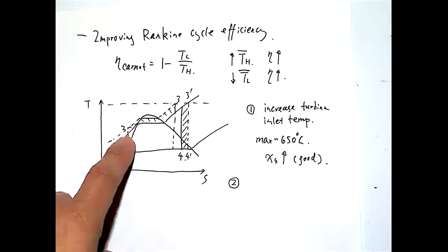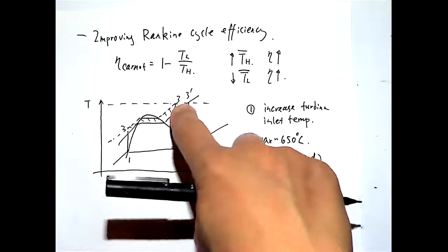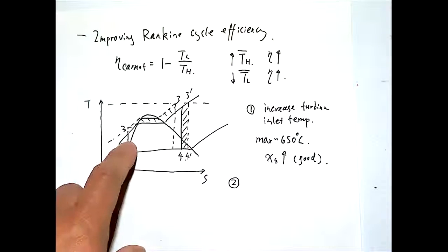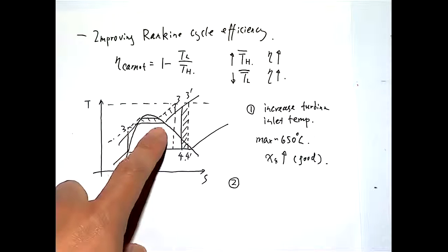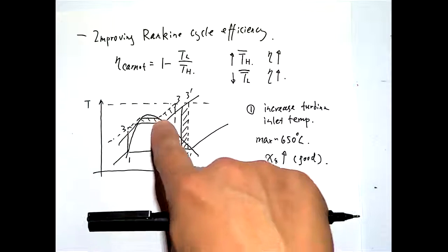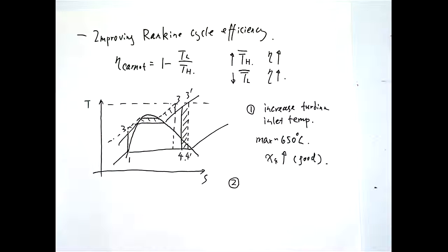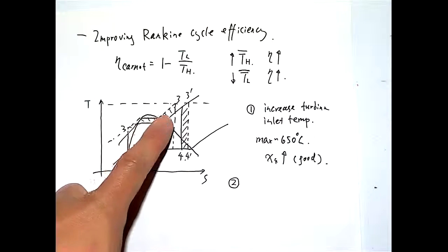So this is basically you raise the pressure up and then reach the same turbine inlet temperature there. In this case, obviously you increase the average temperature during the heat addition, because underneath the saturation dome, the temperature and pressure are correlated. High pressure means high temperature, right? But this case is not necessarily all good. You can have a higher efficiency.